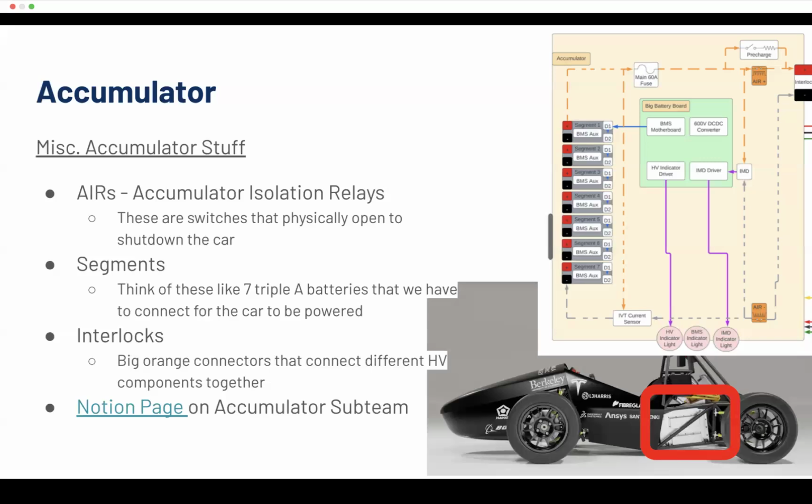And that current can actually weld the AIRs shut. And then if you weld the AIRs shut, right, our shutdown circuit no longer works, because if we remove power, it's been welded shut, right? So much current went through it, so much heat, it melted the two pieces together.